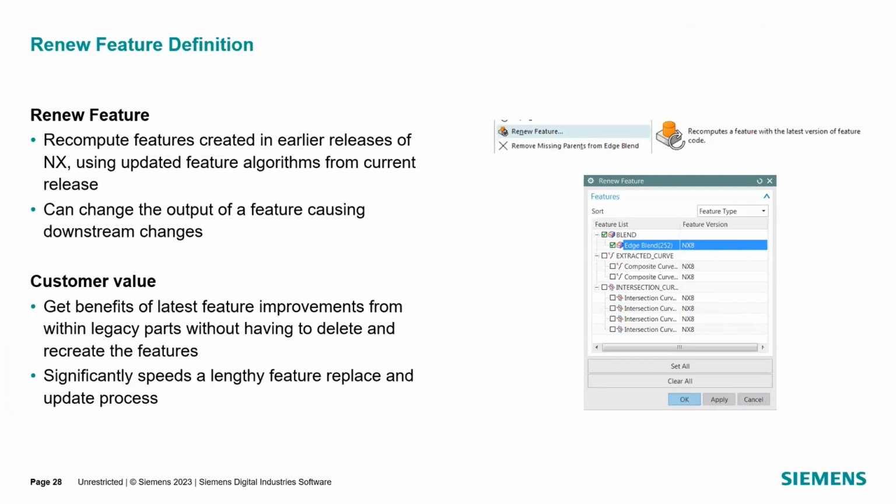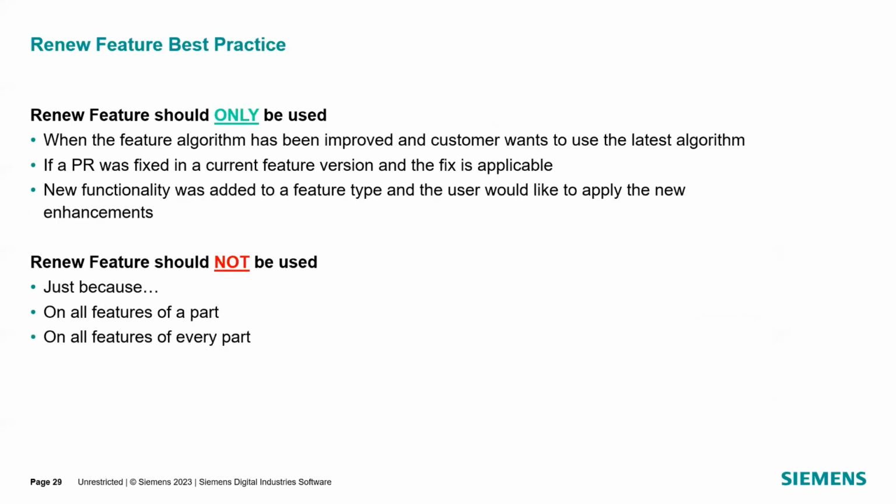Before, it automatically came up. What if I do want to renew that sketch? What would I have to do? We can go to the command finder, and if you just type in renew, Renew Feature will pop up, and you can use that. It basically shows you a menu of the features, specifically the sketches. And if you want to do one, or whatever you have in that particular part, you can update them from there.